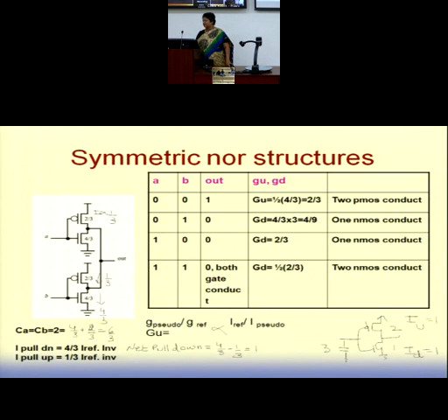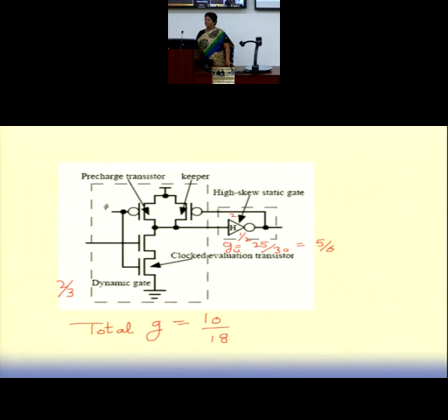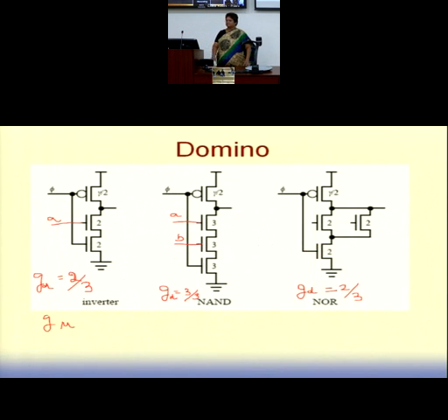So if I look at my gate logic family for a domino CMOS, it's a single stage. You can say domino has an inverter also. Let me say a dynamic gate, because domino is a combination of dynamic and static. So we look at a dynamic gate. As I told you earlier, domino is nothing but a kind of skewed gate.